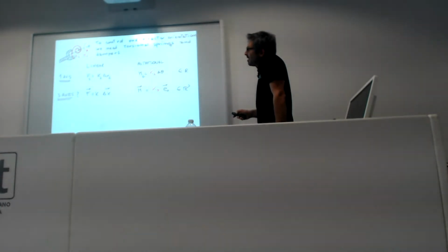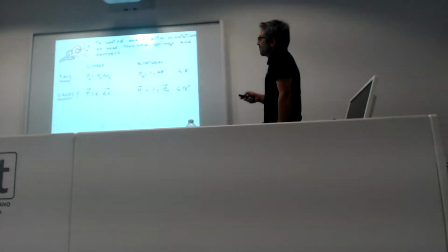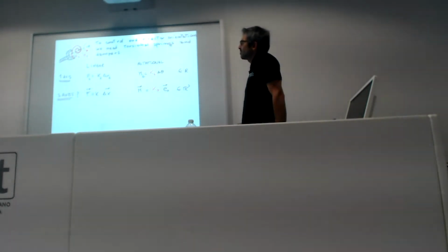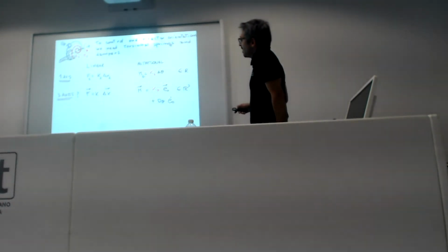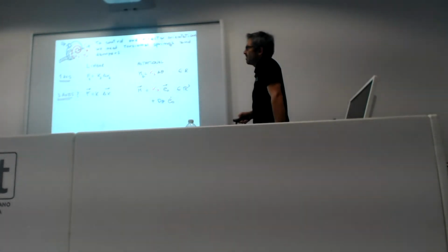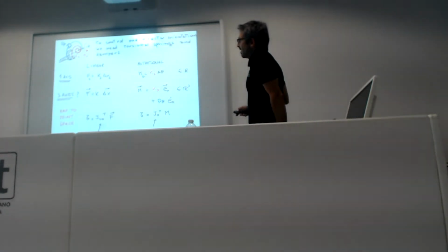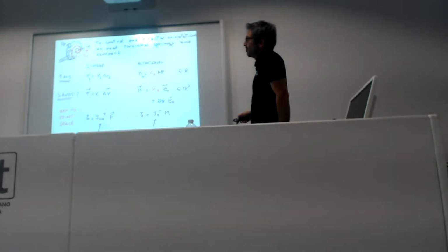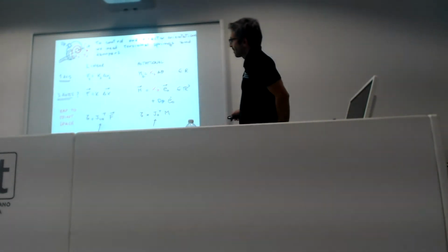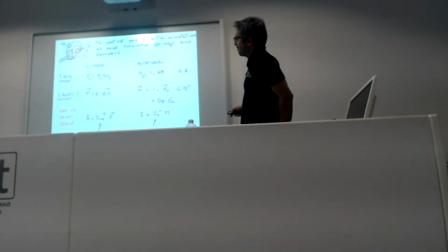This is a 3D vector equal to a rotational stiffness, let's say a 3 by 3 matrix of torsional stiffness gains, times the orientation error, plus some other term, a damping term, for example, times the orientation error derivative. Then, once we have these two, if you have the force, you can map it to torque, as we saw before, through the linear Jacobian, while if you have the moment, you can map it to torque through the orientation Jacobian.